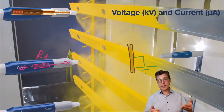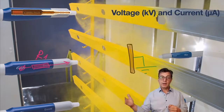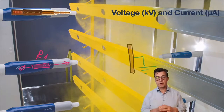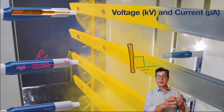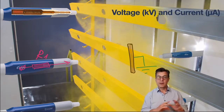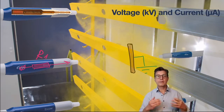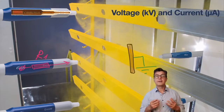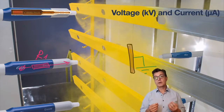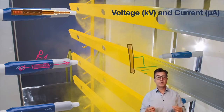There is a multiplier with a resistor inside the gun. That is our electrode number 1. And then we have a second electrode, which is our grounded parts. The quality of the second electrode is no less important than the quality of the first. Whatever we do to improve the charging system, to increase the kilovolts, to control the microamps, all of that can be in vain if the second electrode is of inferior quality. If reliable grounding of the product is not assured, no matter how good a spray system one has, the process will not work.